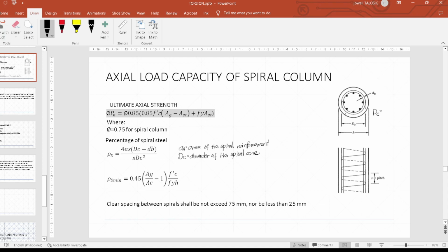Okay, so if we're going to solve for dc, this is equal to h, where h is the diameter of the whole column. Okay, minus, ibawas po natin yung space na to, which is the concrete cover or the steel cover. So dalawa yon ang makabilaan, so that is h minus 2 concrete cover, no?